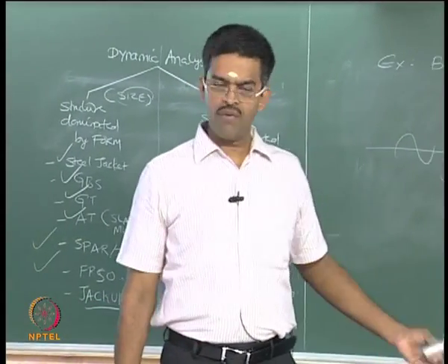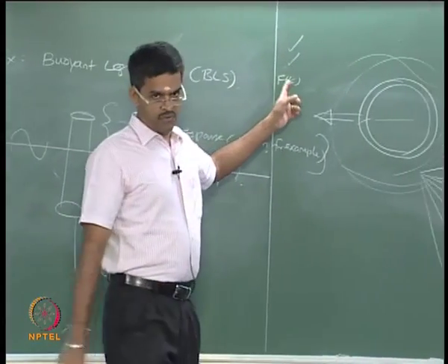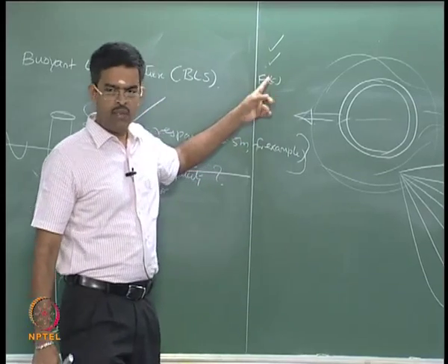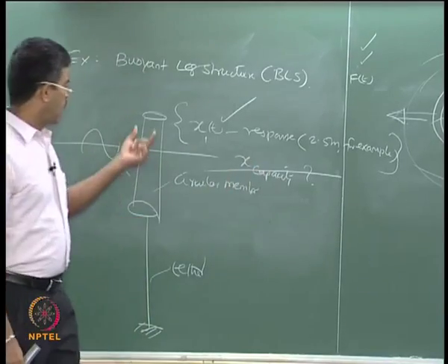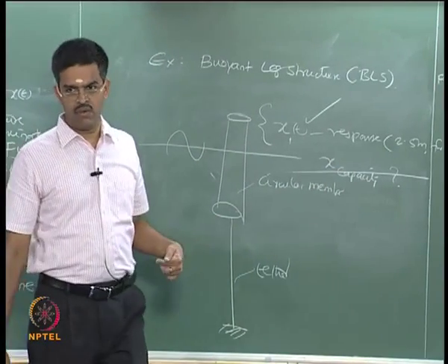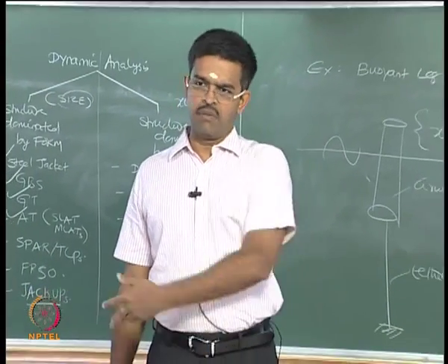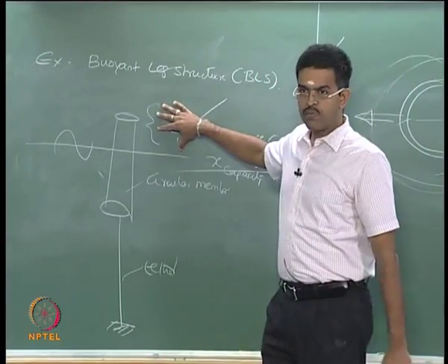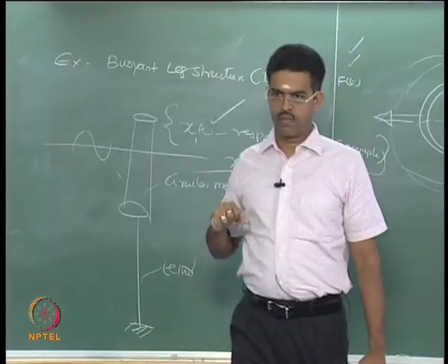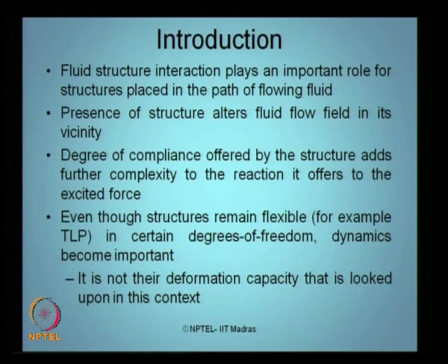One of the sources we have in the offshore structural system is f of t. The forcing function itself can be a non-linear function. The remaining non-linearities can come from large deformations, large displacements, and of course the material characteristics, etc. So if you want to include this behavior in the dynamic analysis, then I should do non-linear dynamic analysis. If I do not want to include them, I simply say dynamic analysis, where I am looking only at the response and not the capacity. Okay, that is what this last point in the slide means, that we are not looking at the deformation capacity, but we are looking at the response. Is that clear?